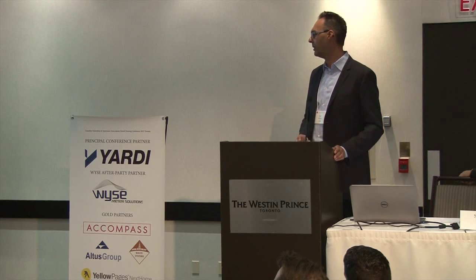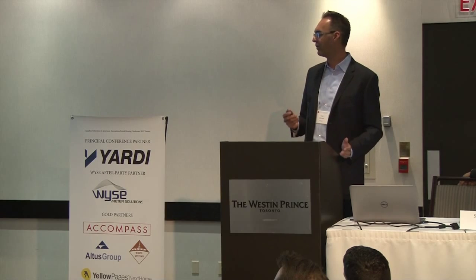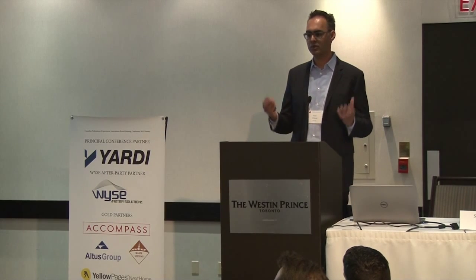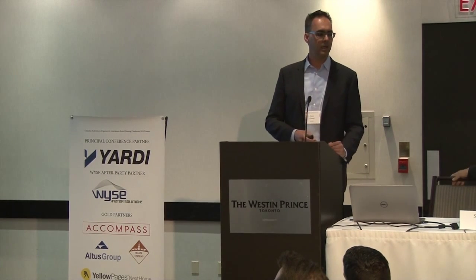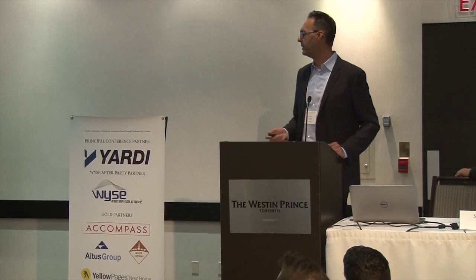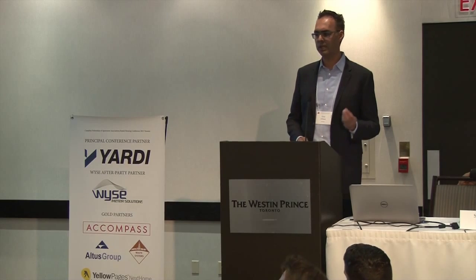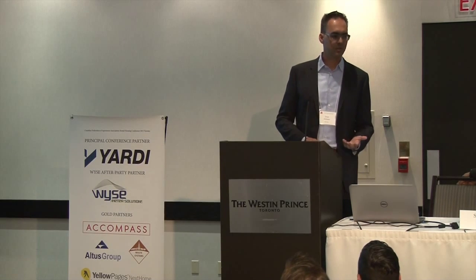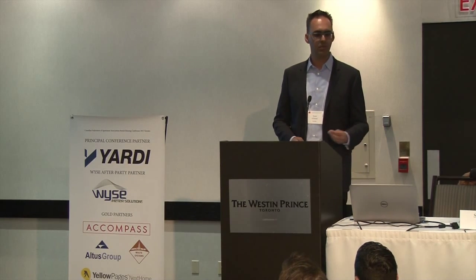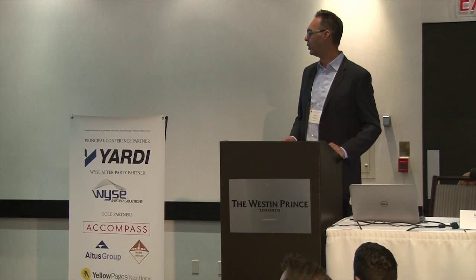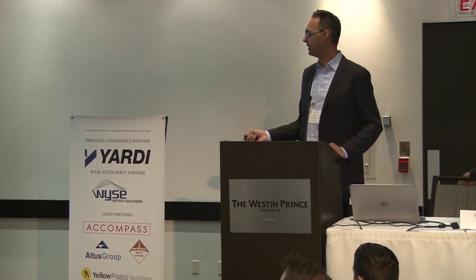And so buildings in the 80s were known for this sort of new construction technique, and they were not well designed. The outer gypsum board was paper-faced. It's prone to getting wet. And as soon as gypsum board gets wet, it just starts to turn to mush. And it's also prone to mold. The steel studs, if they get wet, they tend to corrode out.